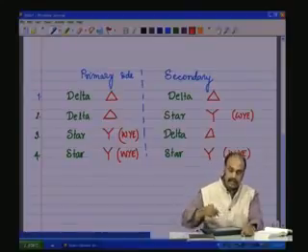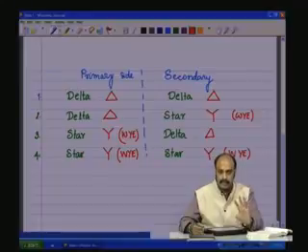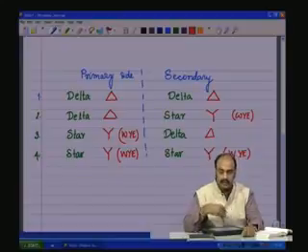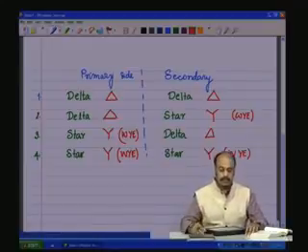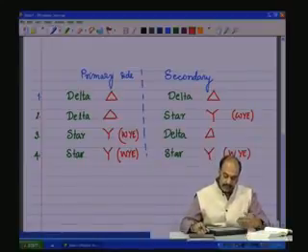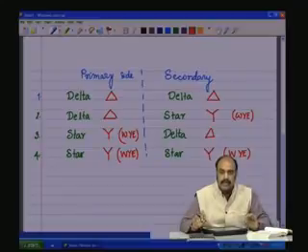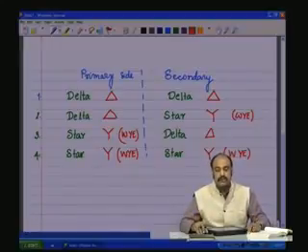So, these are the possible connections that one could make with the three single phase transformers, and based on these types of connections the nomenclature of the three phase transformers is made, that is delta delta, delta star, star delta, star star type of connections. Now, let us take each of these four types, study the various current and voltage relationships across the phase and the line, and also the phasor diagram for each of these types of